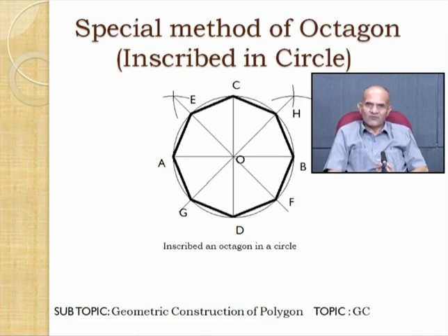So here we have used the geometrical constructions of the angle, how to bisect the given right angle. And with the help of these geometrical constructions, we have divided the circle into 8 parts. Each included angle is 45 degrees, and we have drawn the octagon. First we have drawn 4 vertices, so each angle will be 90 degrees. Then again we have bisected this 90 degree angle, so we have got the 8 vertices and each angle is 45 degrees.